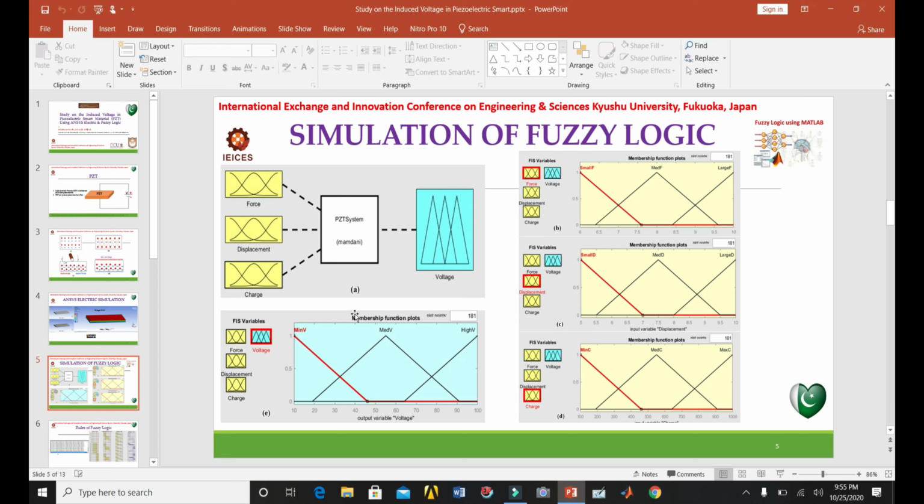We can take expressive power in the Mamdani model. We can take less flexibility in the Mamdani model. And in the Sugeno model, we have no output membership functions, no output distribution, no defuzzification, we have a continuous output surface, and less interpretability, but we have more flexibility in the Sugeno model. So I have used the Mamdani model here for its broad system.